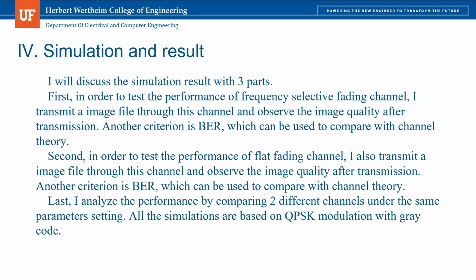Second, in order to test the performance of a flat fading channel, I also transmit an image file through this channel and observe the image quality after transmission. Another criterion is BER, which can be used to compare with channel theory. Last, I analyzed the performance by comparing 2 different channels under the same parameter setting. All the simulations are based on QPSK modulation with Gray code.